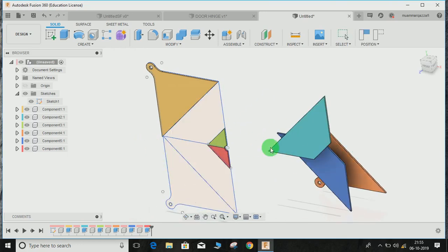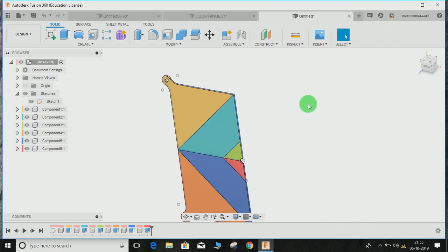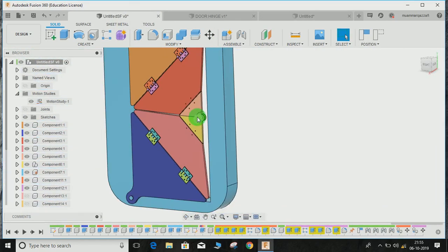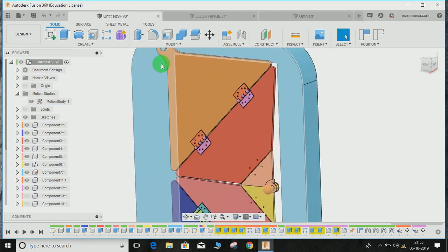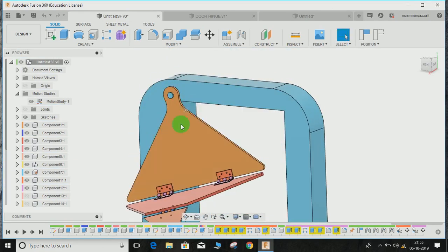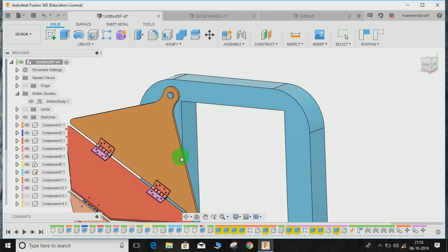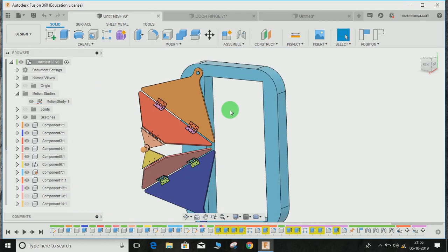So next thing we have to do is make the wall. Basically this part is needed so that we can fix this part on this wall. So we have to draw a rough wall and a hole through it that will represent the walkway through the wall. So for that, again go to the front plane, click on front plane, and there's no particular dimension, as this is only for representation.